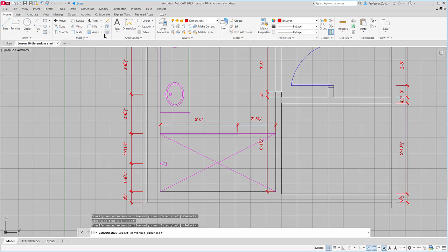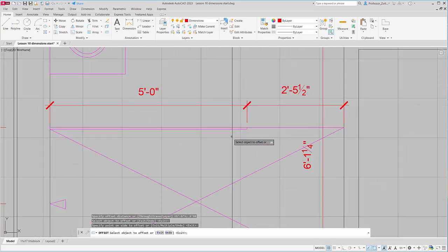All right, simplest technique, offset. Pick the easier of the two numbers, 2 foot 10 here, and I'm going to use this line as a temporary construction line. There we go. Now, easy here, we're just going to use stretch, modify, stretch. I start on the bottom right or the top right, and I move to the left.